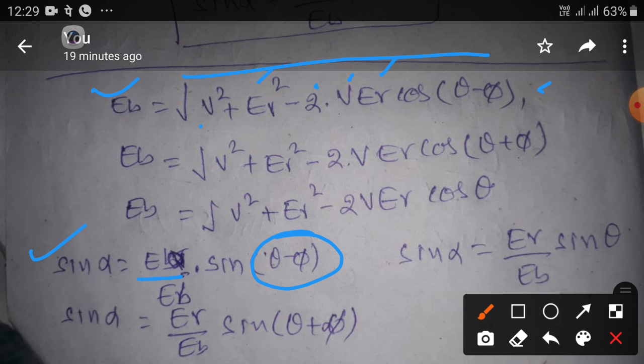If the motor is overexcited, that is, DC supply is given more, then the current drawn from the supply is at leading power factor. This is the voltage, the current goes in this direction I, and this is phi, leading power factor.